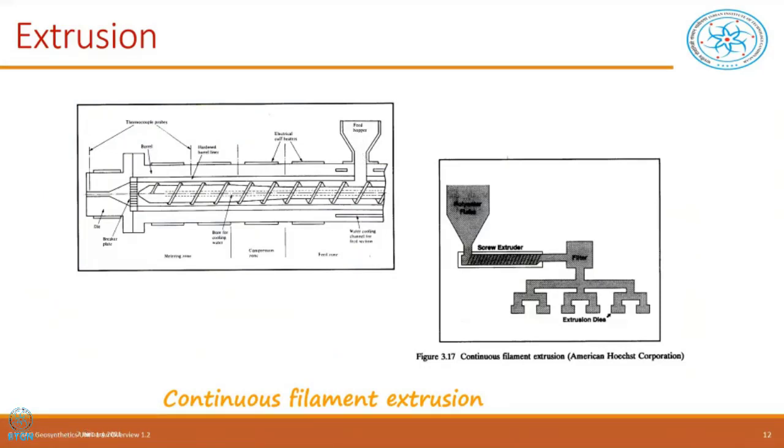For example, looking at PET, that is polyester, it comes in chip form. These are almost like sugar granules. So they come in a bag. Before we start making anything out of it, we have to add all these chemical additives which we already mentioned. So we get it mixed first. That means if we want to make a particular geosynthetic fiber, naturally, we get it mixed earlier in some other plant, get the raw material of polyester or PP or whatever it is, add the necessary chemicals, mix them thoroughly, and bring these small chips to this site. Once you do that, you put it in the hopper.